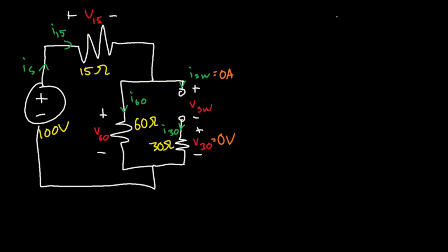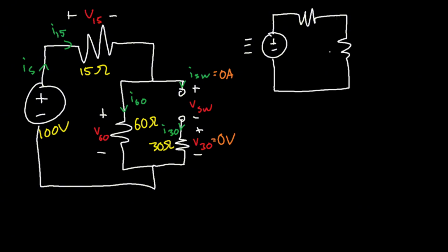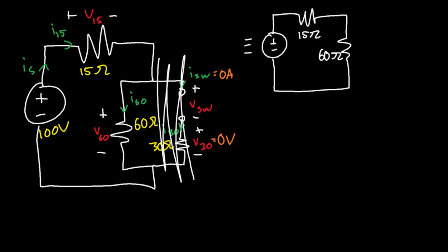So nothing really electrically is going on this path of current. Nothing really is going on this side since there's no current and there's also no voltage. So what do we want to do? Well, let's just completely omit it. But let's not forget it, of course. So what we really have is our 60 ohm resistor left over after omitting this sort of section of the circuit.